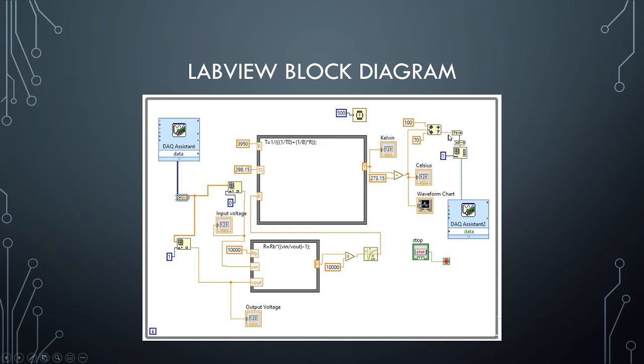So I ended up converting it to a number, then converting the number to an array. This first function here is Boolean to number, and then number to array, and then reformat or rearrange array. And this one is just making it a one-dimensional array. And then that is accepted by the DAQ assistant. So it's a one-dimensional true-false array, pretty much.